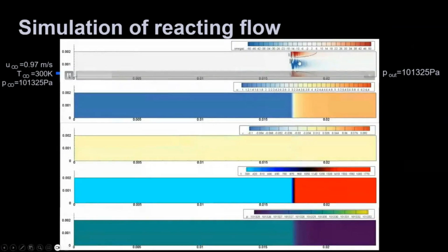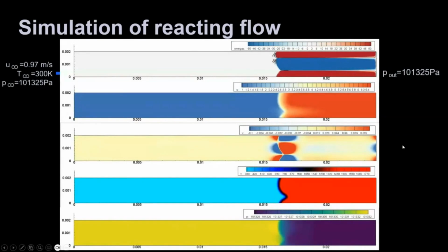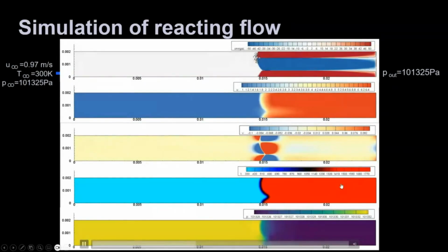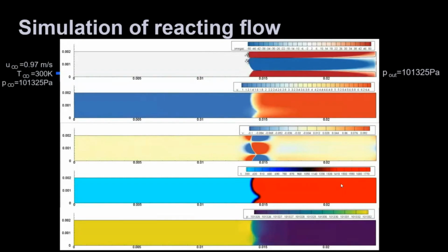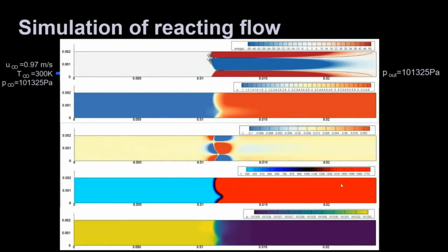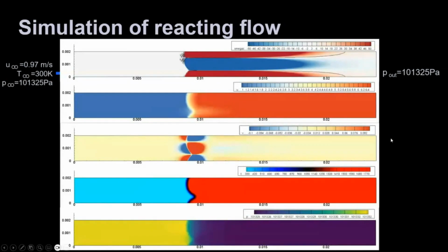When the vortex interacts with the high temperature zone, we see the flame front is highly distorted. In the meantime, we see the steady flame starting to progress in the upstream direction, which means the whole combustion process is highly sensitive to the fluctuations from the oncoming flow. That's why when we design engines, we need to be careful with the fluctuations.